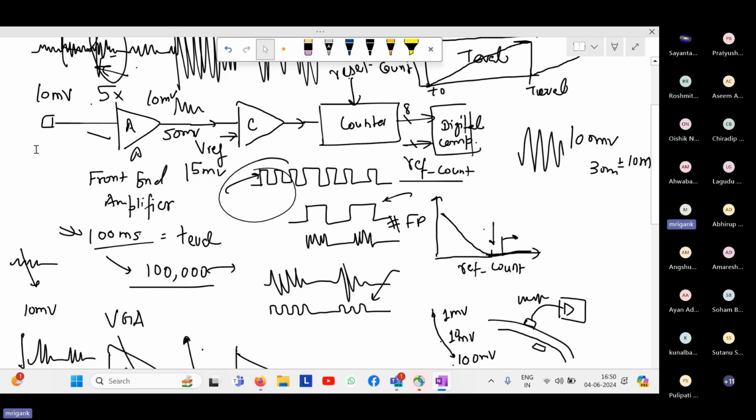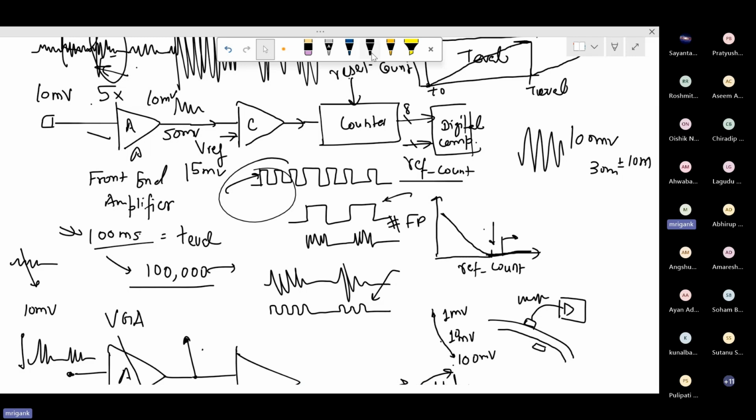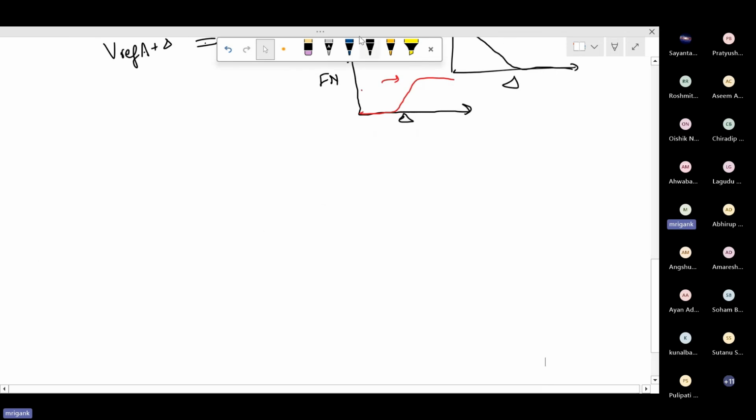that will not require a very precise amplifier. Also, another thing: are we concerned about the linearity in this case? Are we very concerned about the linearity and distortion? For the amplifier, remember the open loop gain comes from the accuracy factor, that is how accurate the gain should be, right? Because closed loop gain accuracy depends upon the open loop gain, right? So for the amplifier we have beta, 1 upon beta, where A naught is the open loop gain. So this approximately is 1 upon beta, provided A naught beta is much bigger than 1.